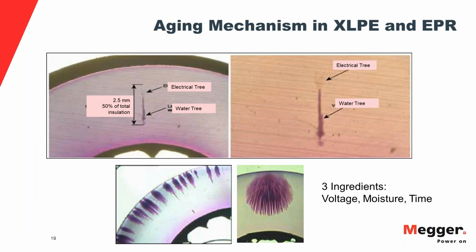And then when we say aging of these cables, in solid dielectric cables it's a little different than in PILC cables, because there you have cellulose degradation and drying out, carbonization of the oil and the mass and everything. But in solid dielectric, both in XLPE and EPR, the main aging mechanism is treeing, water treeing.